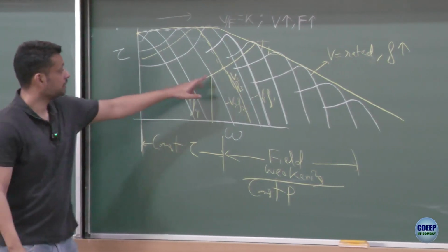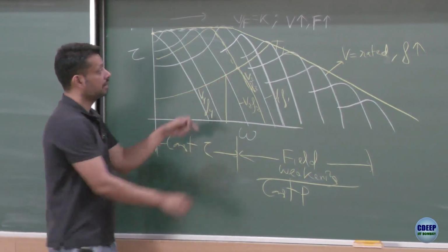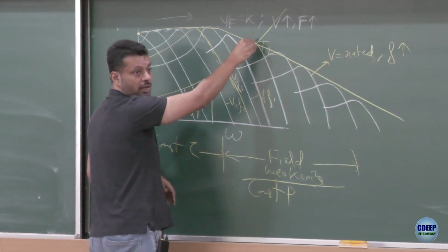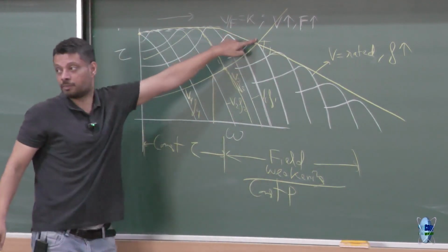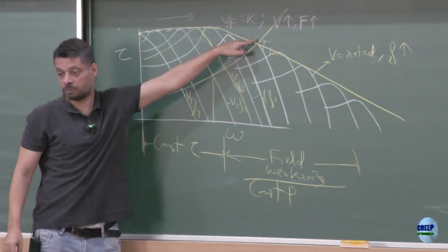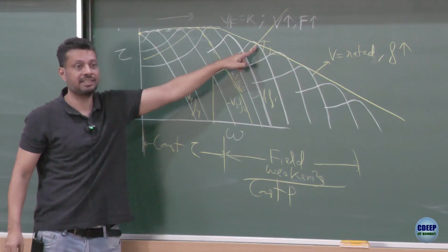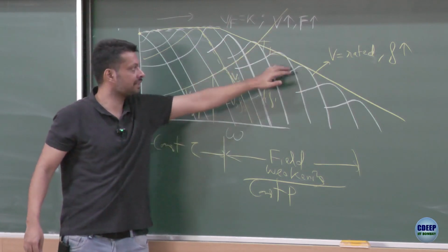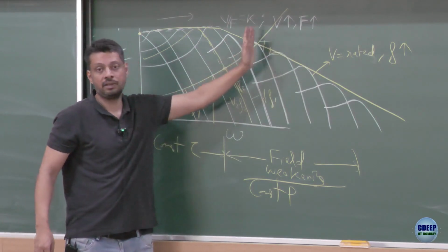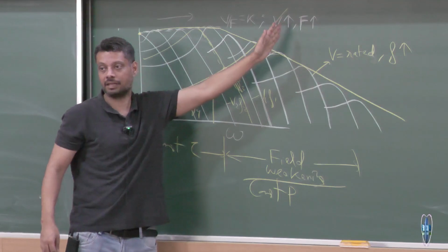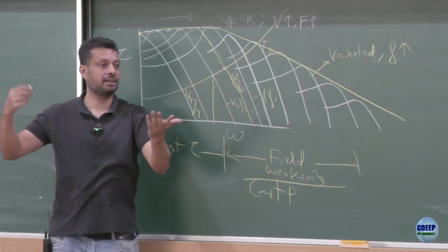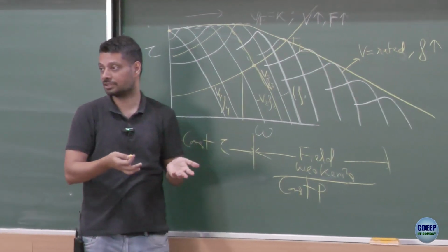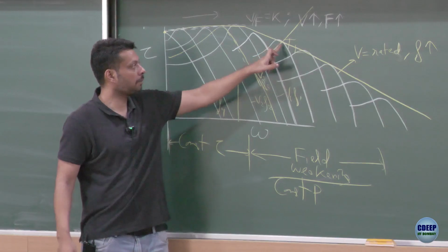So now if this was the characteristics, the original one, you can operate maximum up to this speed, because this is the farthest intersection that you can find. You can set your voltage and frequency to be even higher, but since there is no intersection point between this curve and this curve, it would not operate at higher speed, right? So even if you are setting whatever 100 hertz, it doesn't matter, your rotor will not take you there. It will actually be a standstill position. It will not even move. But you can maximum go up to this point.